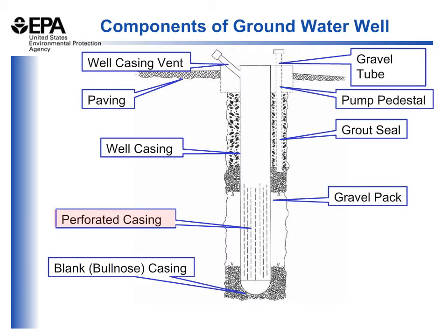In a bedrock system, a well casing is often installed from the ground surface down to a particular depth, and below that it may be an open hole where the well is drilled through hard bedrock and there's no need for a casing to keep the hole open. In this situation, there may not be the need for a well screen because the bedrock may be strong enough to hold the hole open, and you want to ensure that you have the ability to get water from as many fractures as possible to increase the yield of the water that you're pumping from the well.